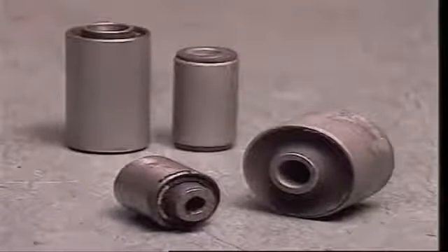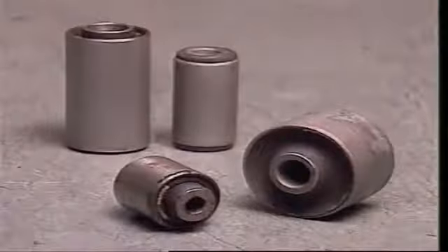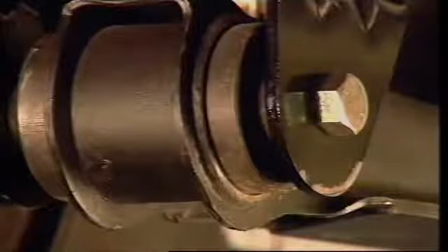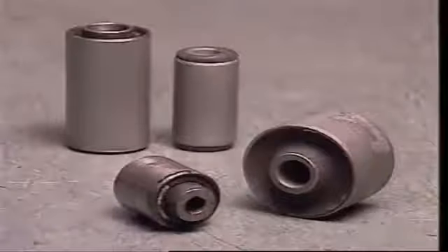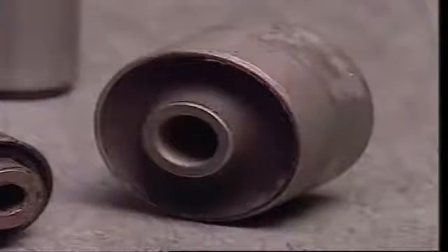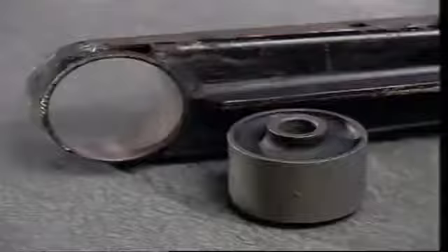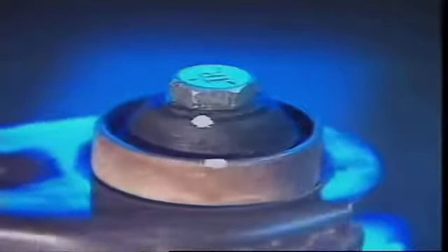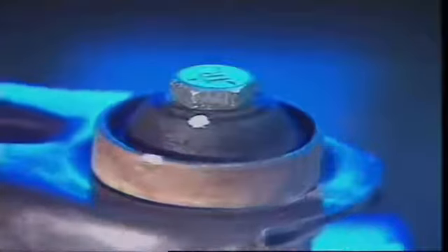Metallastic or rubber bonded bushes are normally used for the front eye of the spring at the fixed shackle point, and also in control arm applications. The bush has a steel outer casing and inner sleeve. The rubber medium is bonded to both to provide flexibility between them. The outer casing is normally pressed into place in the component. Relative movement between the casing and the inner sleeve causes the rubber to shear without tearing.